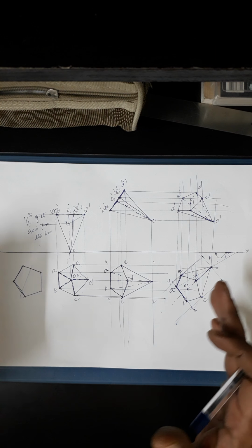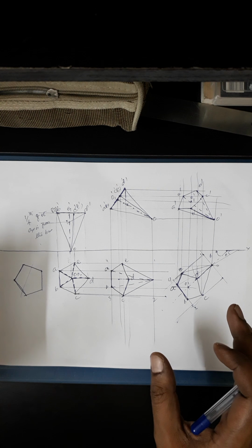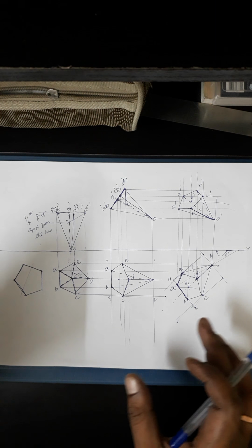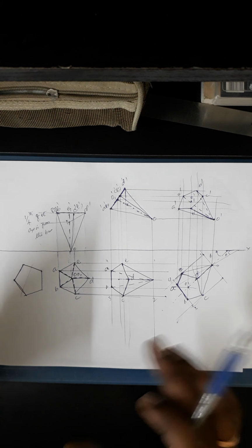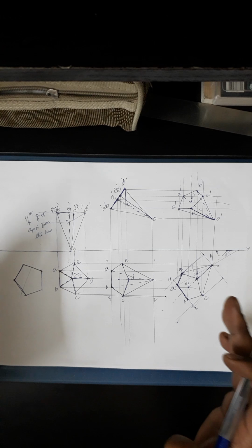There will be a lot of procedure to draw. There will be a maximum work to draw because you have to draw in freehand ellipse. Similar to the projection of planes where you have drawn that circular lamina appearing as something like an ellipse. In the same way here you're going to have 12 points to be projected in all the sides. That way the time taken to solve the problem will be more, otherwise it is same as the prisms. Cylinders and cones will be same as the pyramids.